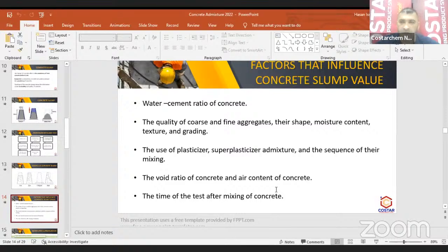So what is the type of air that we really like? The type of air that we really like and encourage to be added in our concretes is called entrained air, and you can go up to 12%. Now we said the ideal mix is 6%, but you can go to 12%. So how exactly will air enhance my concrete durability?